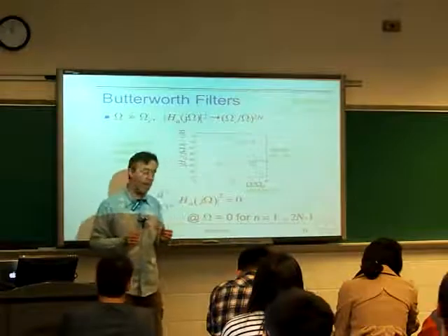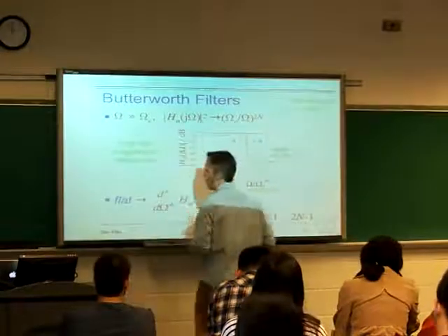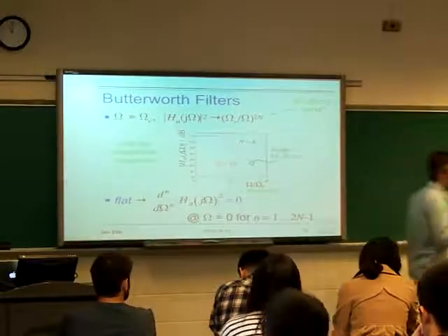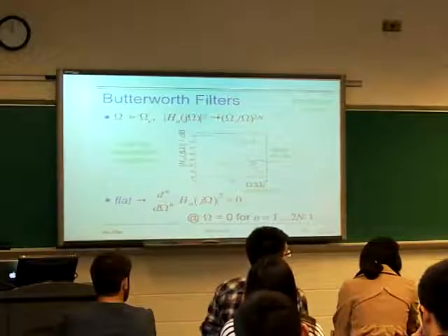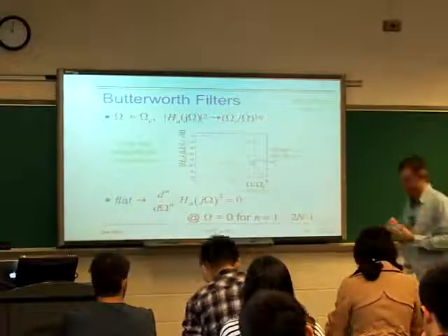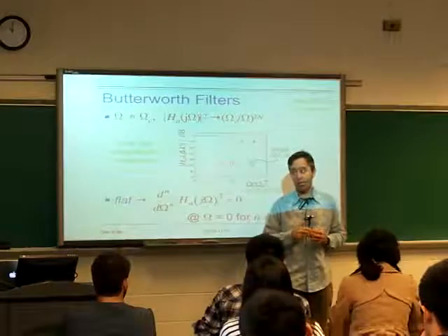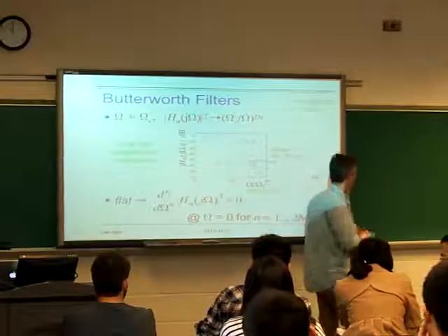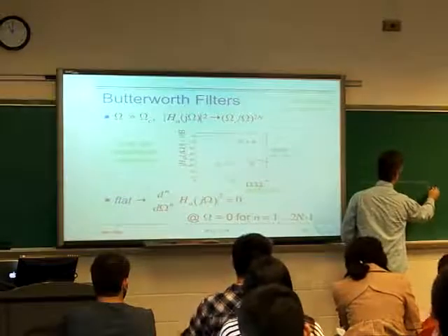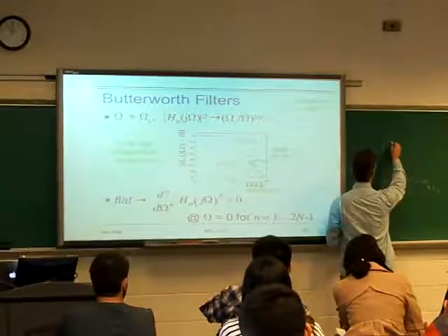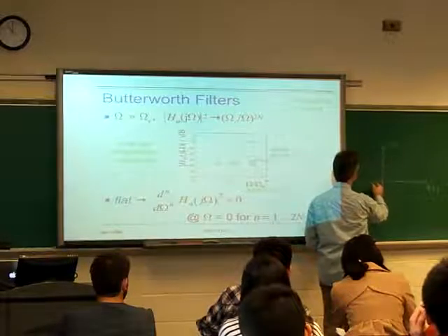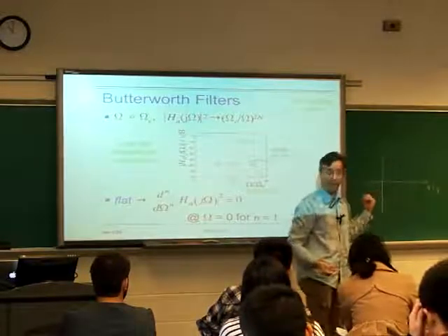But in general, that's going to be the case because, okay, I don't know if this is going to help or not, but the whole argument about the geometric way of figuring out what's going on in the z-plane works in the s-plane as well. That geometric argument was just about how to understand the behavior of a system expressed as a polynomial on a complex plane. So if we have the s-plane now, this is the real part of s and the imaginary part of s, and then I've got some H of s, and that H of s is going to have a bunch of poles somewhere. They're going to be in the left-hand half plane because we want them to be stable.